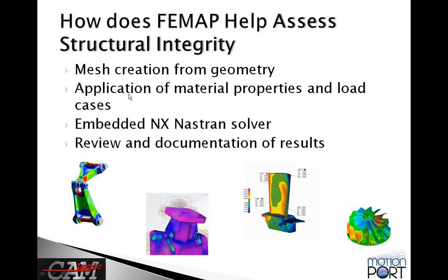Second, we can then apply this information we have on material properties and the load cases, both applied loads and the constrained locations. Loads can be things like point loads, but also things like pressure on different faces of the geometry.